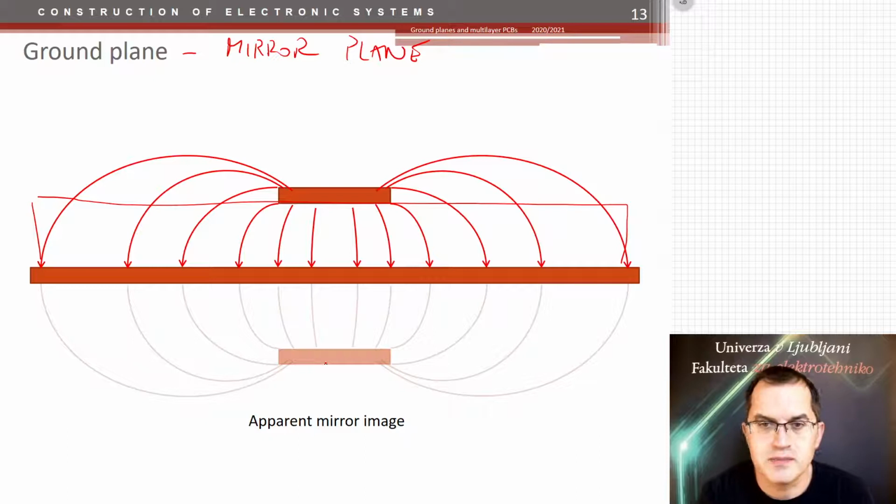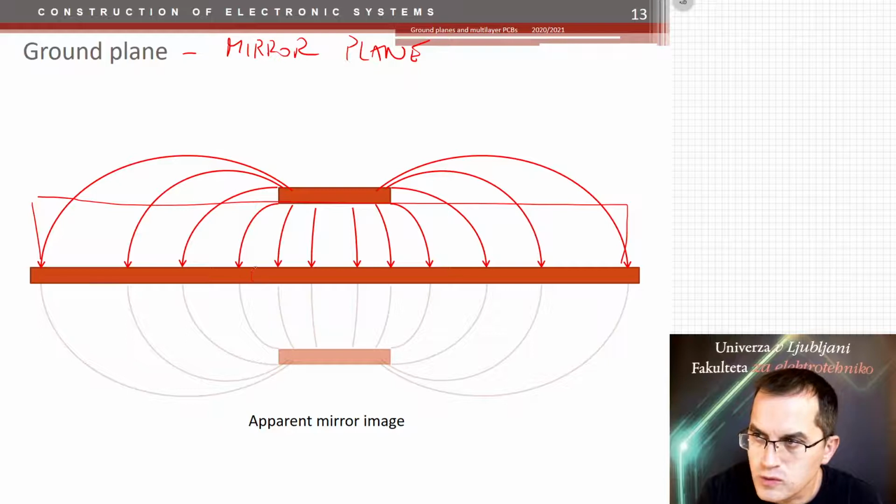Now, what does that mean? The line or the track has a very defined geometry. And this very defined geometry with a continuous ground plane defines its basic electromagnetic properties. And the ground plane, of course, also provides the so-called return path for the current that flows here.